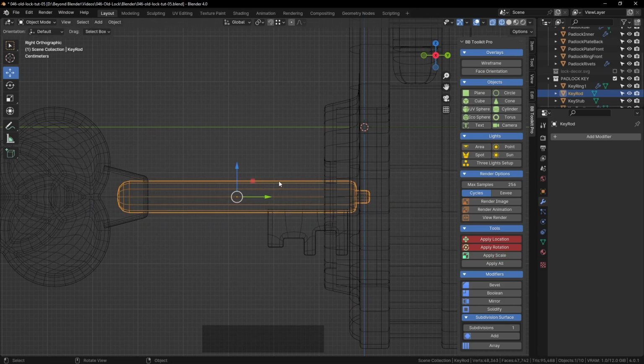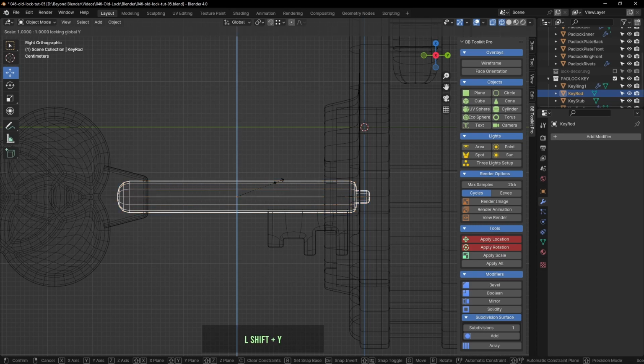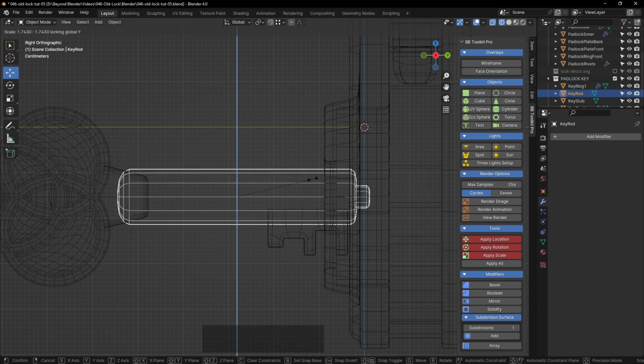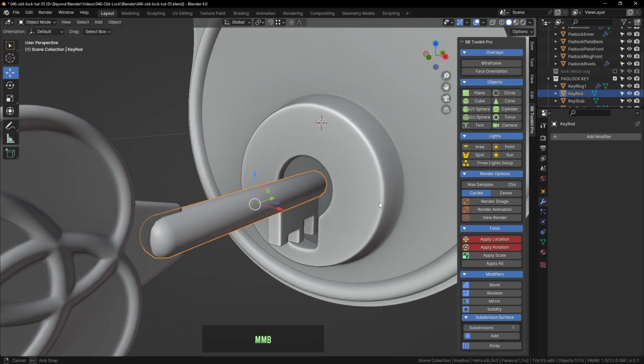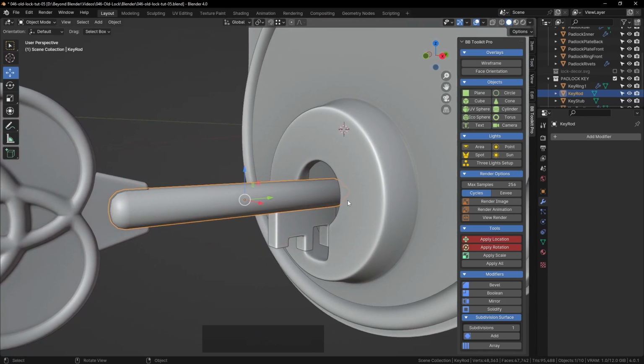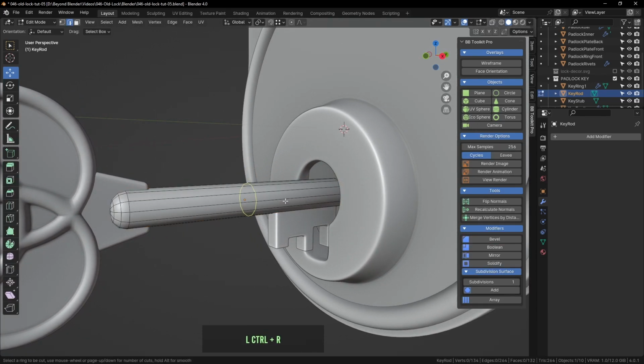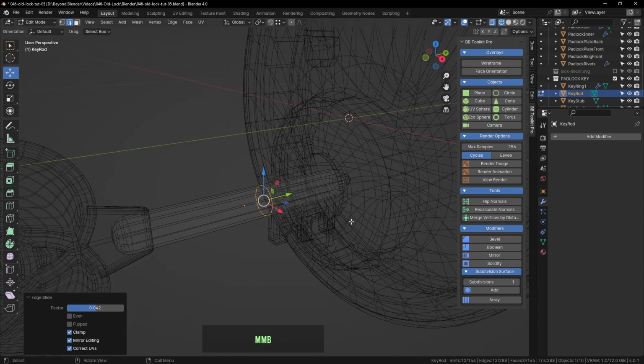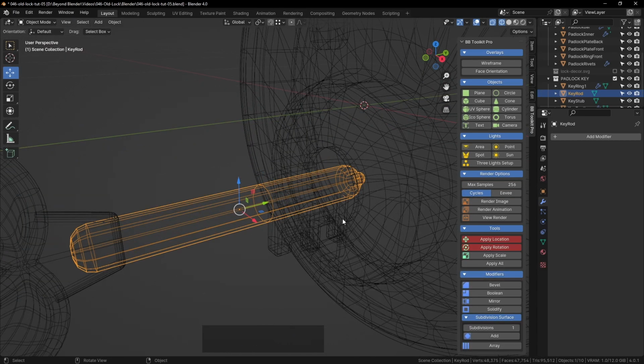So what I decided to do is, well, let's beef it up initially, actually. And then when I come to my senses in a minute. But yeah, I'm not going to do that because that's a terrible idea. So we need to isolate it at the front. So I'm going to put an edge loop just there with Control R, maybe just past the teeth part there. And the reason I'm doing that, I'm going to isolate the front part with the back part.